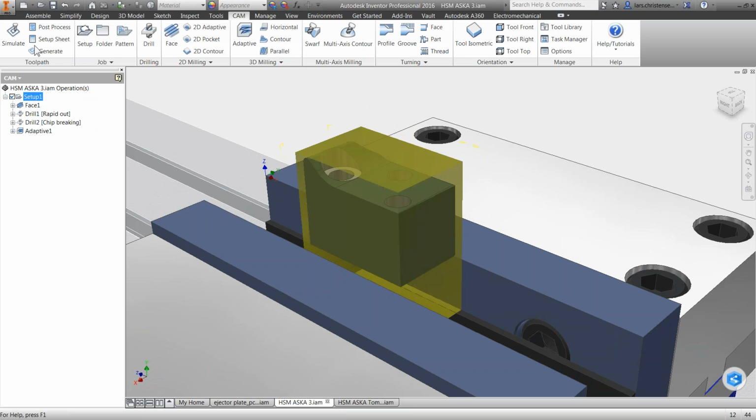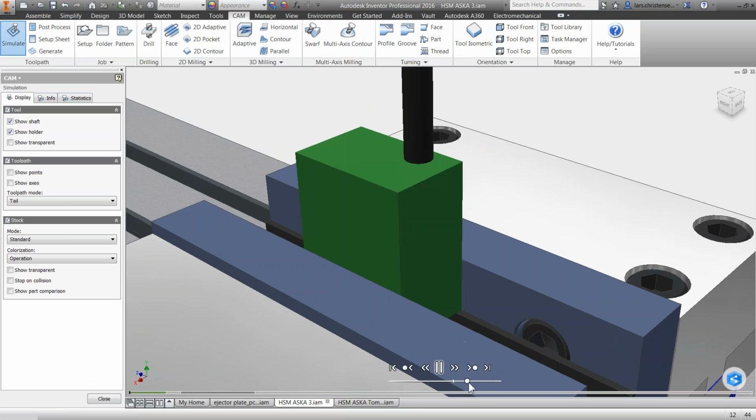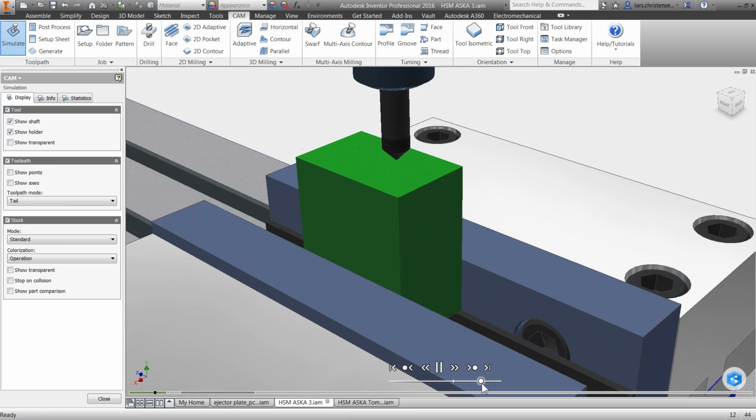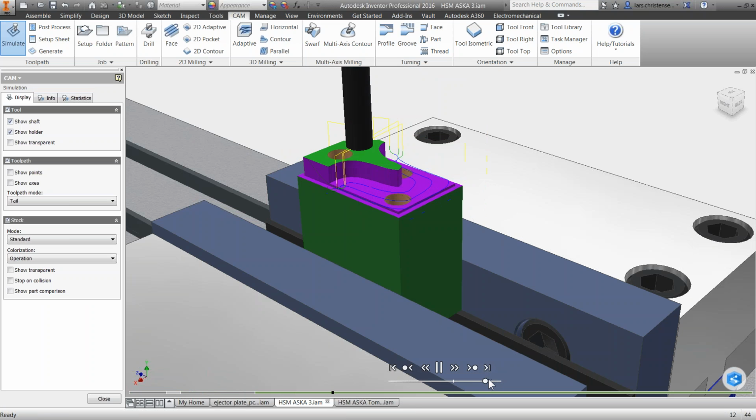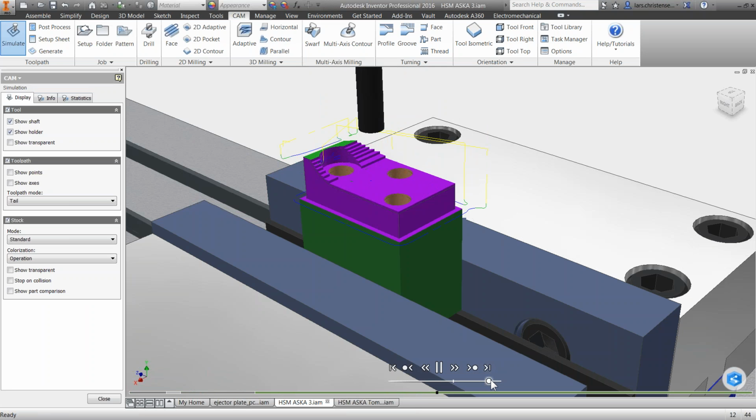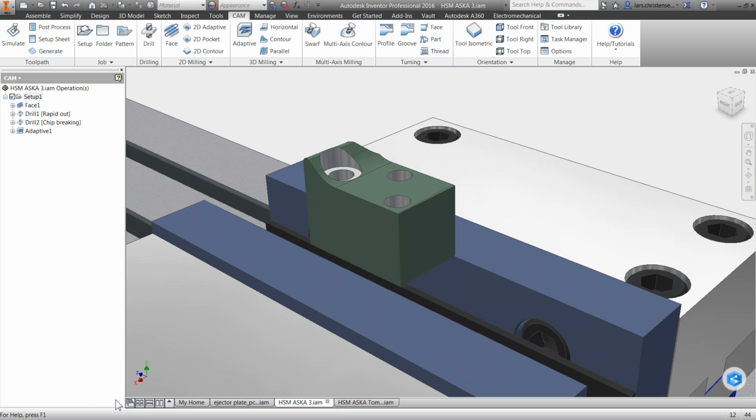Why don't I just show you really what I did here, might as well, right? So I used the facing operation, but just with a normal end mill. Drill some holes, and then I roughed out the part so we can put a 3D surface on it. Now, the reason I wanted to show you this is because if any of you venture into this, like I said, with other CAM software I've used, it was really a struggle for me to try to find out how to do that. Inside of our software, we have a lot of great 3-axis toolpaths that you can use.